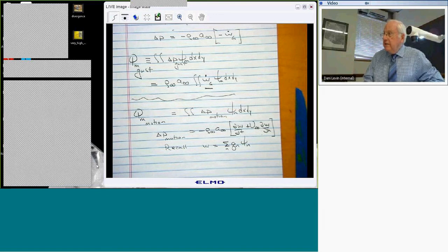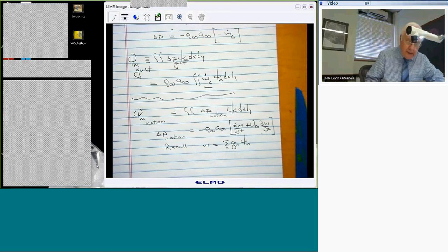So even though we used eigenmodes for the structure, which was nice because orthogonality meant we could look at one mode at a time as far as the structural terms, when you get to the aerodynamics, the modes are going to be coupled anyway. Nothing to be done about that. Well, in principle, you could actually find the aeroelastic modes and invoke orthogonality again, but no one ever does that because by the time you found those modes, you solved for the flutter solution. So why bother? Anyway, let's move right ahead.